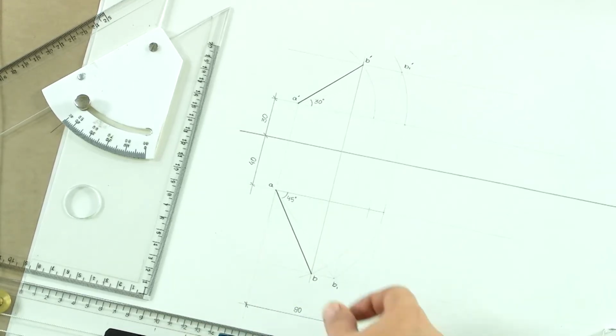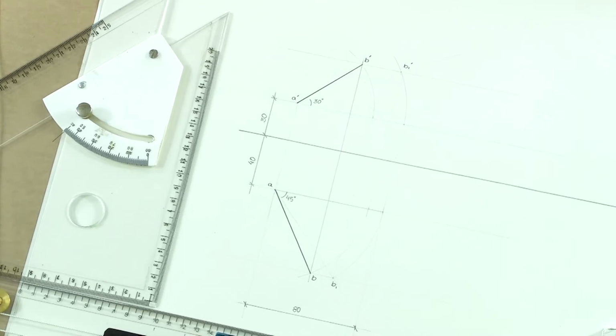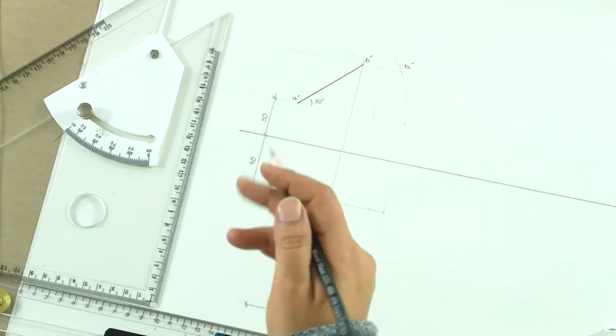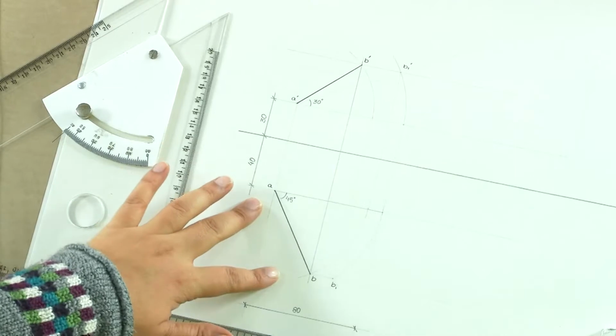Sometimes you would find that these lines are not necessary, but the direct use of this one is when you calculate the shadow angles when you are studying climatology. In that case, the angles which we are seeing here, inclined to both the planes, are the angles that the light rays, the sun rays, are making with the horizontal as well as vertical. And in that case, how you design your shading devices and how the shadows will be calculated will be determined based upon how you arrive at the projections of doubly inclined lines here. It is exactly a similar principle.